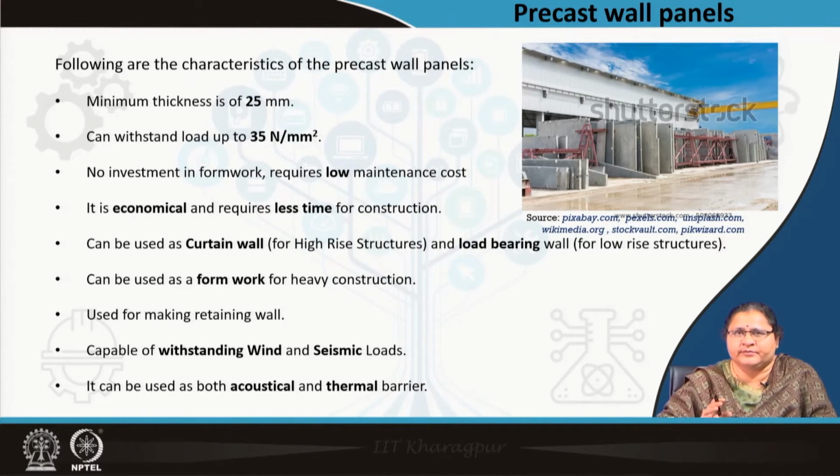It will be between the floor to floor height, the dimension of the doors, windows, the panel number where it will be done. So, a total schedule, like you prepare a door window schedule, a panel schedule has to be made, prepared, and it has to be tagged with the drawing, like x axis and y axis we have A, B, C, D, E, F, 1, 2, 3, 4. So, every panel will have a number, and which panel will sit where, it has to be followed with the drawing.